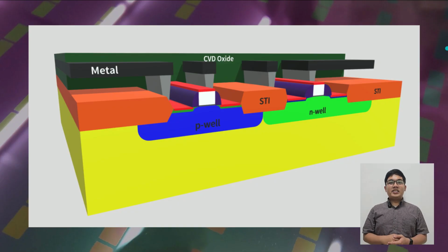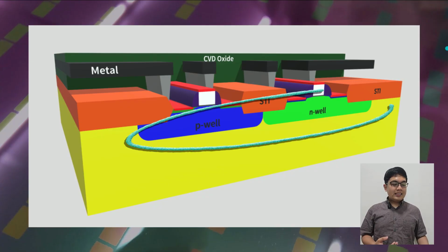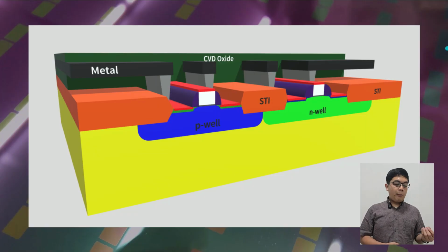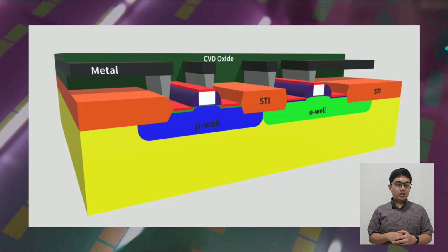Next, we look at the 3D structure of a CMOS. Here shown is actually a CMOS that is produced by the twin-well silicon gate process, which is the one that we'll be talking about today. Physically, we can actually see the complementary nature of the CMOS. Here we can see in the blue and the yellow a P well and an N well that is implanted on the same substrate.